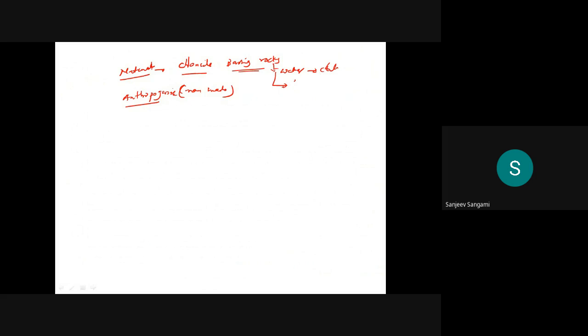Normally groundwater is the source. So if you are getting chloride in groundwater, it is due to a natural source. In Dharwad district, Upin Betigeri is one area where even if you dig any borewell, you'll get chloride in groundwater. It is natural because faults or bearing rocks are there. Once rainwater comes in contact with those rocks, you get chloride in water.